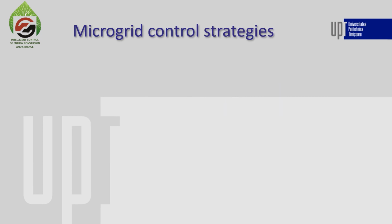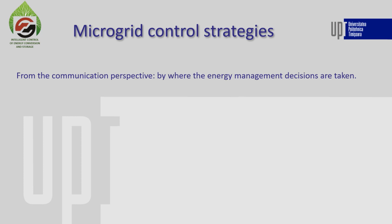Microgrid structures are commonly categorized from the communication interface perspective, more precisely by where the energy management decisions are taken. Within these categorizations, microgrids can be centralized, distributed, and decentralized.